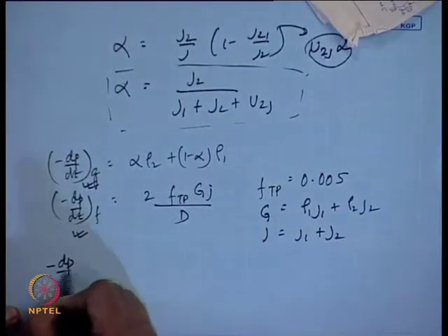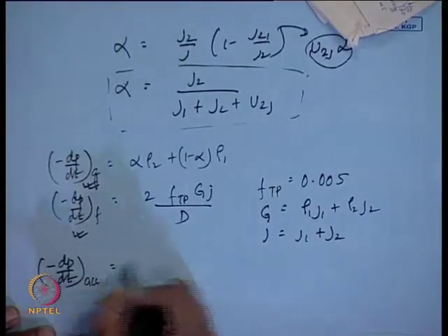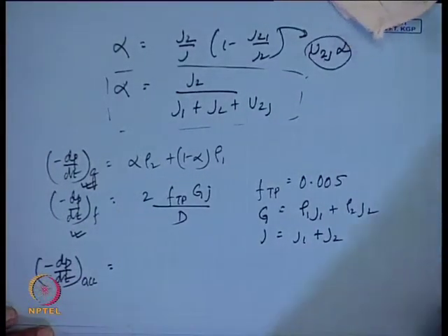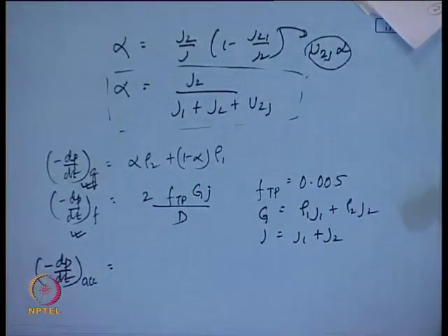Now, the next thing is finding out the acceleration pressure gradient. Now, one small catch I would give here. What you have to check is this: it is given that the exit pressure is atmospheric pressure, and you are required to find out the entry pressure. Now, you have to check whether the flow is under sonic conditions or not. If the flow is under sonic conditions, then naturally the outlet pressure of the pipe will not be the atmospheric pressure; it will be the pressure corresponding to Mach number equal to 1. Please remember this thing. These are small catches.